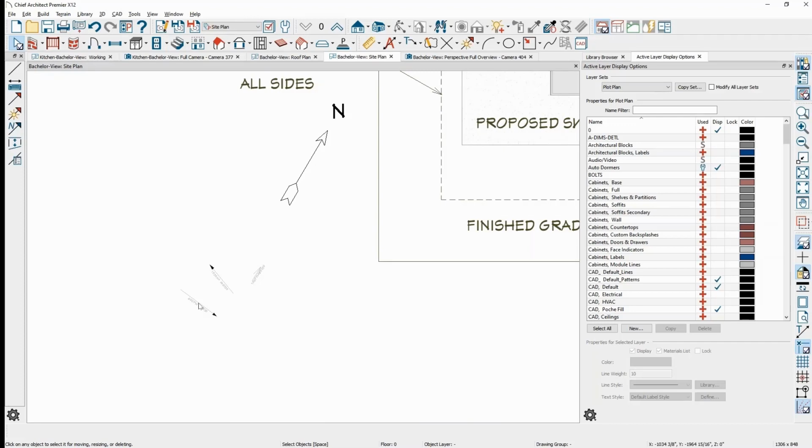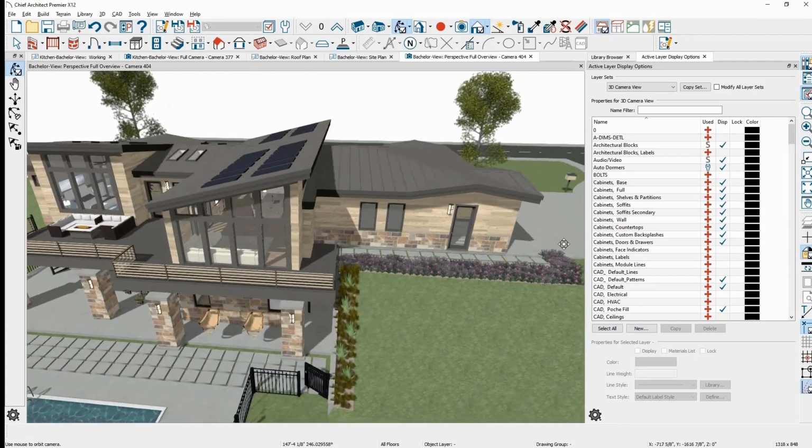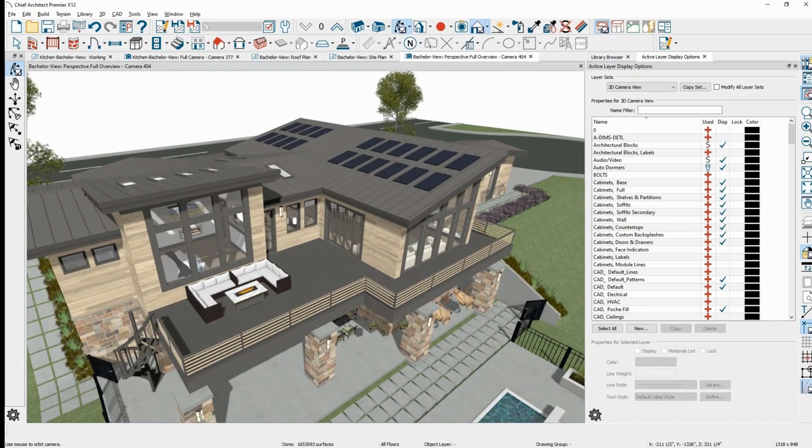Yeah, absolutely. That's awesome. It's just I wasn't too sure because previously, I'm semi-experienced and been using Chief for quite a while, but I just put one sun angle in. I didn't realize by adding additional sun angles, you had that option to be able to change. What I was doing was going back and resetting the times. So obviously the difference between us at 9:30 in the evening in summer is massively different to, you know, it's basically 4 PM in winter. There's like a 5-hour light change.